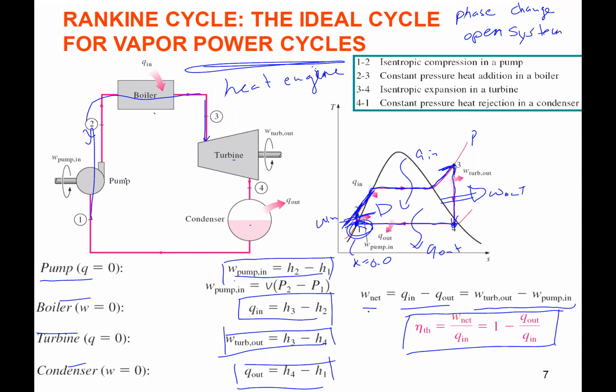Right, so then we also have the steady flow reversible work we can use for the pump. That comes from this integral equation for steady flow reversible work. For the pump, we can assume the water is incompressible, so from 1 to 2 the specific volume can go out, and we take the specific volume out and integrate, and you get v delta P.